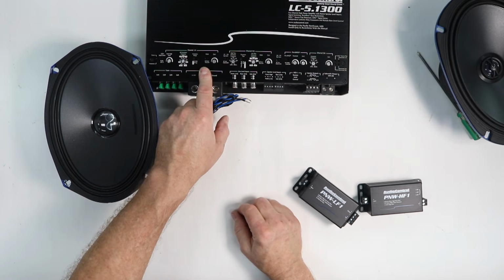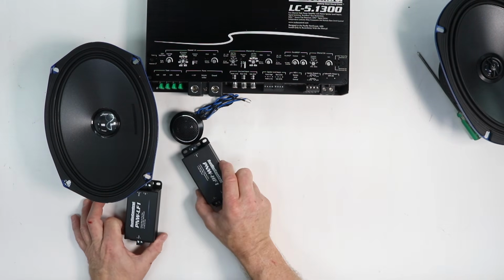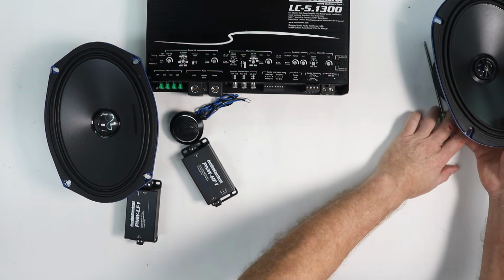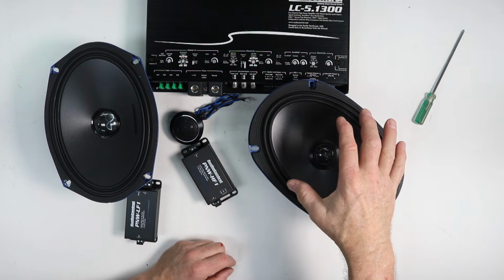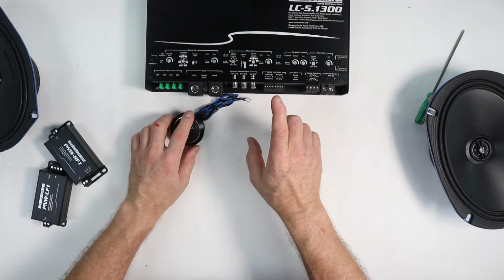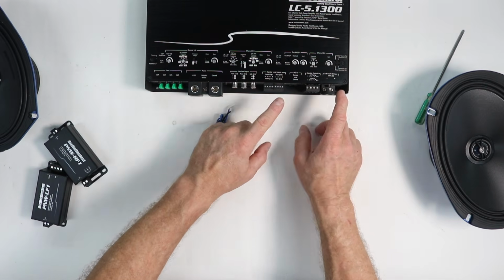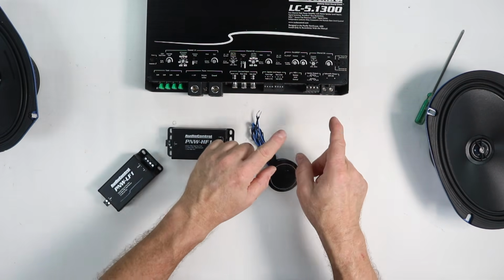We will set that high pass crossover on this to 80 Hertz, and I will run my low pass and my high pass passive crossovers to these, and then on channels 3 and 4 I will also make a high pass filter and power these. Kind of gotten the idea of what's going on here. The other thing to keep in mind is an active crossover is done before the output, whereas the passive crossovers were done after the output.